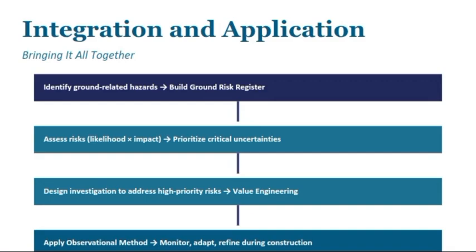However, during construction, you will now have your observational monitoring. After all these things, the next thing is observational monitoring. Why? You want to check the actual ground behavior. You have to continuously monitor it. If observation differs from prediction, then you get to the next stage, which is adaptive management. So corrective actions are implemented throughout the process.